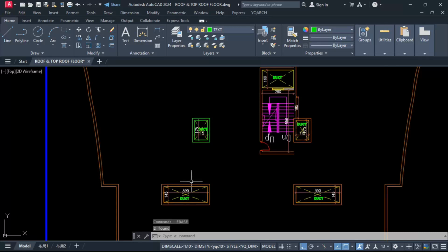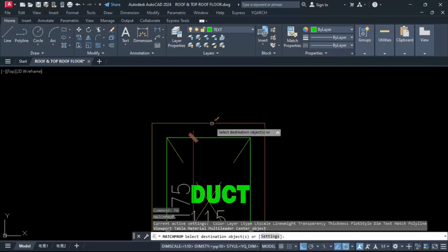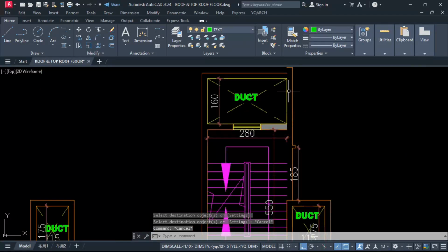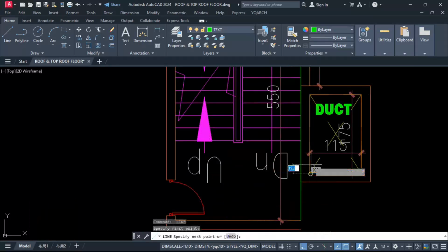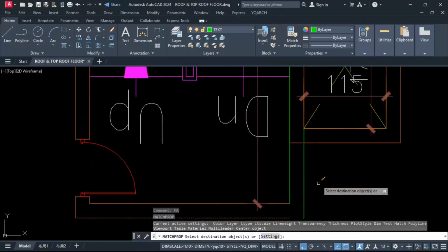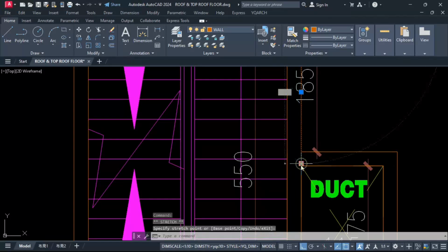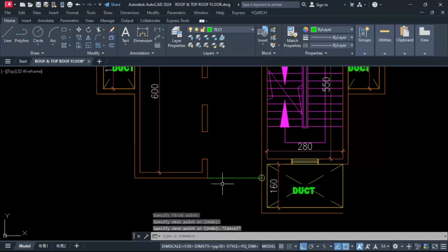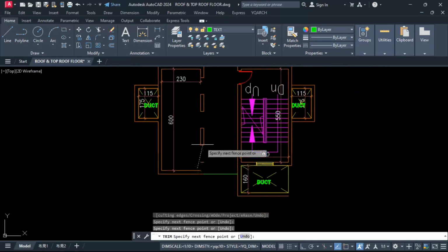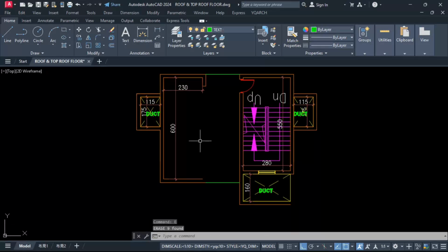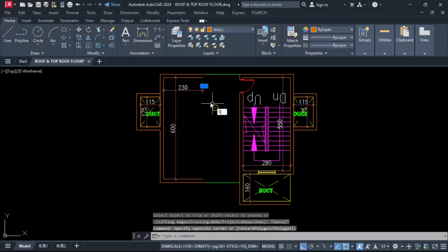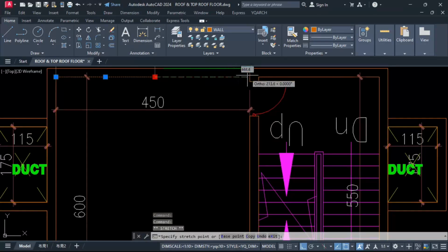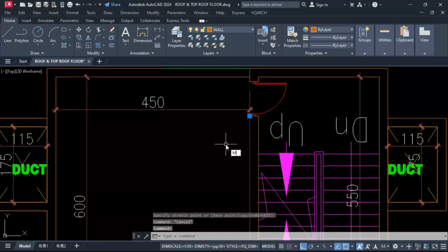So this is our exact OTS, our opening over the slab. This is okay. Let this line go straight to here. So one line will cover here and one line will cover here. And simply join this, okay. And here we will connect this wall and cover this area as a machine room, okay. The rest, let's remove and join this area, okay. We can keep one door here to access inside the machine room, and the staircase door will go on the other side, okay.